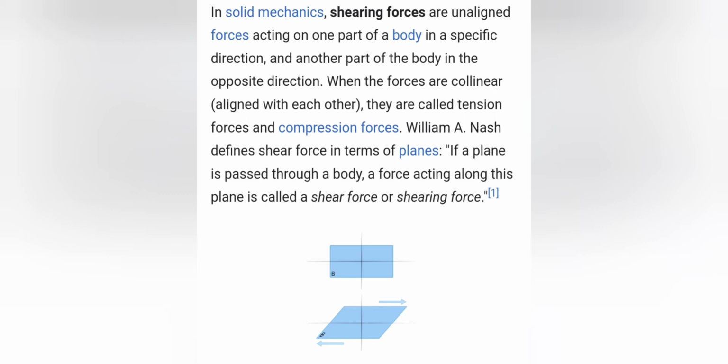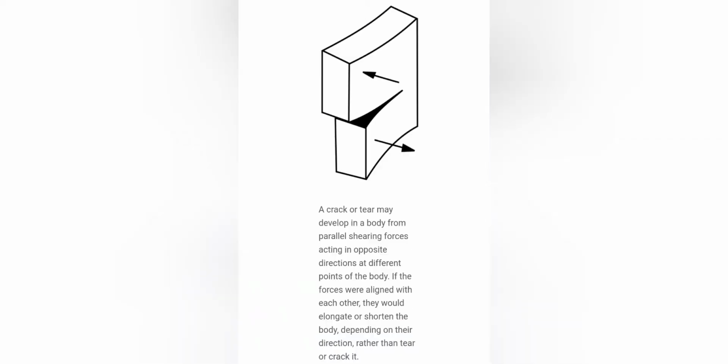Now let's assume a concrete floor slab in a building supporting a column load with load W. The column will punch into the slab if the slab and the reinforcement in it are not able to resist the shear stresses. Similar thing will happen in an isolated footing resisting the soil reactions from the bottom if it is inadequate to resist the shear forces. These two examples of failure modes in slab and footing are called two-way punching shear failures.